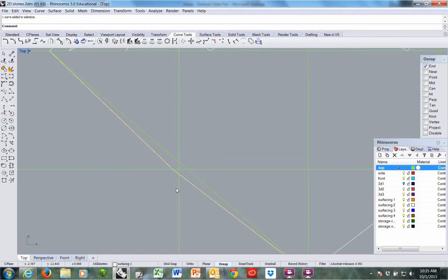but actually I need to draw that bump based on intersecting with this curve here. So I'm going to just turn on my points, F10 like we did in our tracing. I'm going to grab that point, M-enter to move. This is the first time we've done precision movement, so this is good. I'm going to hit M-enter, gives me my usual point to move from. I'm going to snap right onto that point.